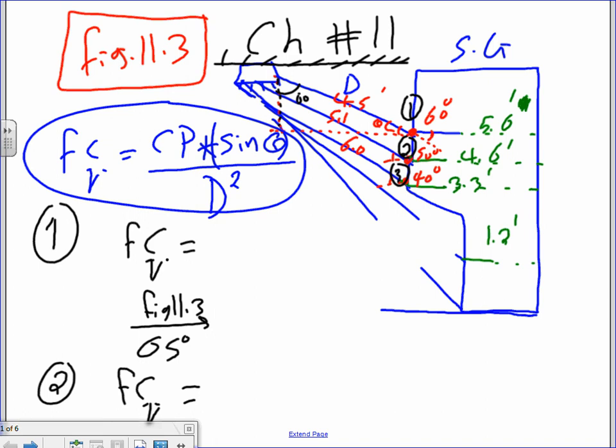Okay, do me a favor. We're going to do calculation about the vertical foot candle. I have a switch gear here, and the code requires a lighting fixture in the electrical room. So the lighting fixture is shining at the face of this switch gear. They're giving me the distances, 4.5, 5.1, and 6.0, between the lighting fixture and points 1, 2, and 3. And they're also giving us the angle between the vertical and the light, and the distribution of the light on the face of that switch gear.